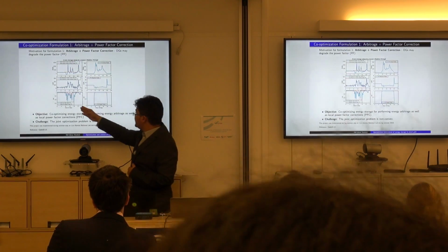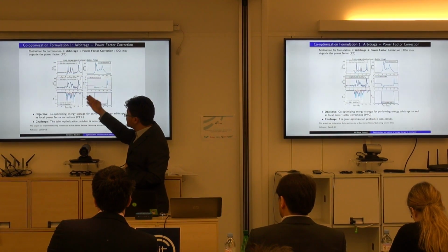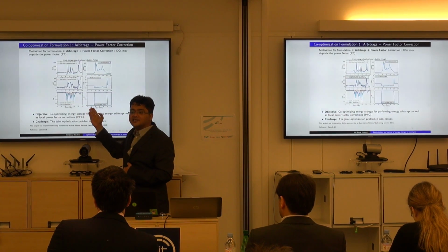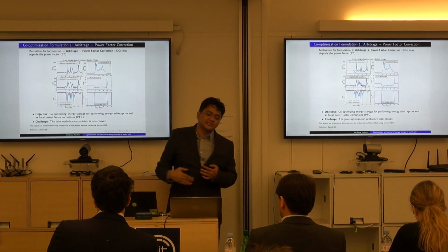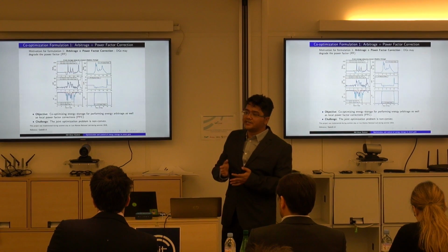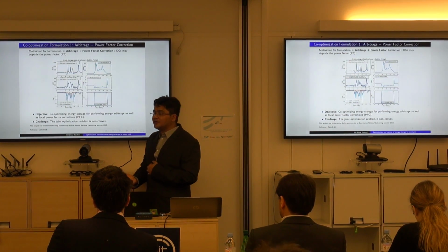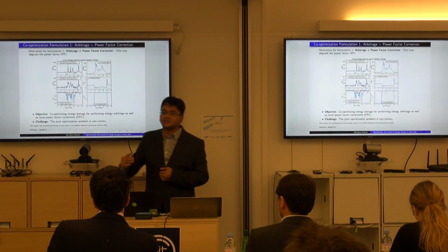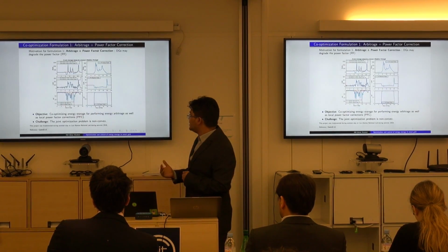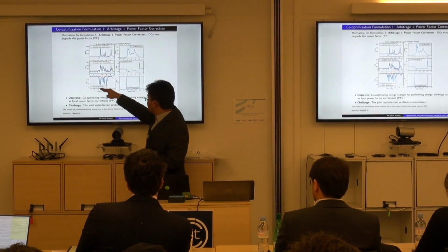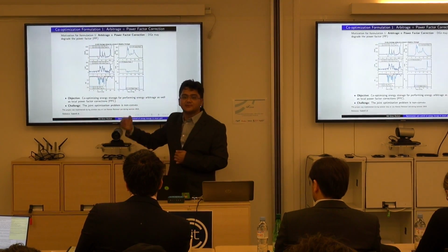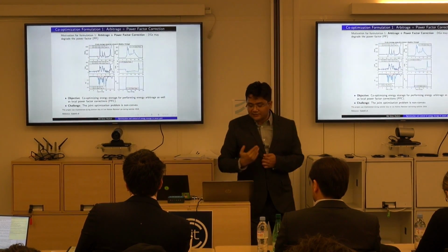What we see is that because of the integration of solar in this case, the power factor during the day significantly deteriorates. Now consider, as in the case of Madeira, that one of the branches has up to 20% renewables. In that case, the power factor seen by the substation significantly deteriorates, and it goes all the way to 0.5 in this case, but it can go even lower.